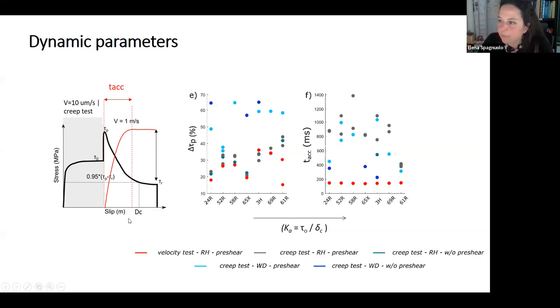The TH, that means in a sense the acceleration, is obviously constant for the velocity experiments, but it's quite variable for all the other lithologies. It's impressive that for this material here, which is the tufaceous clays, this is pretty small. So that means that the acceleration is very, very fast. Instead, in this case, for example, the silty clays, it is quite large.